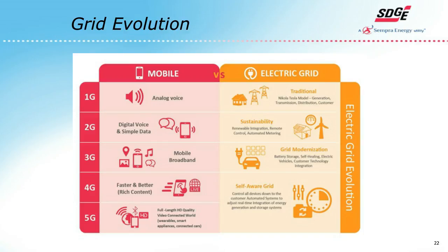In particular, it used to be that the only way we knew that there was an outage was when customers phoned. And it was really pretty interesting because we still get phone calls at 2 o'clock, 3 o'clock in the morning. You think no one would be up, but indeed they were. And now we're getting that same information from our AMI system. We've talked to a lot of people around AMI. They think that you're going to get notification much earlier and therefore have worse performance characteristics from a safety perspective, but actually the opposite is true. You dispatch the crew sooner, and you actually know when they turn off. And so there are a lot of interesting operational efficiencies that have occurred via our AMI deployments.